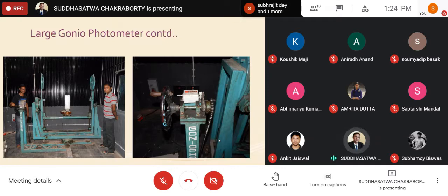If we recall the coordinate system from our last few classes, the only change between C gamma and B beta is that there is a 90-degree shifting of the luminaire in the vertical plane. So here you have to calculate mathematically how all the angles get shifted. I'll measure the data in the B beta form, and finally by angle conversion, by coordinate shifting, I'll change all the C gamma to B beta and all the B beta to C gamma. So that mathematical calculation we need to do, but it is quite possible.